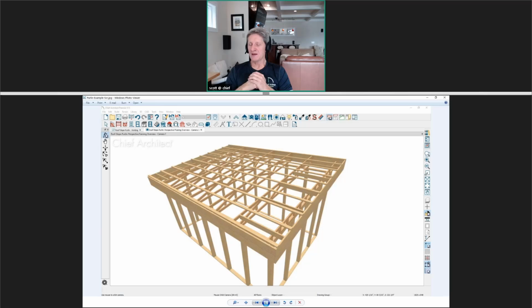Yeah. So the beam currently is basically going to follow whatever your roof is set up as, and on your roof, you can't by edge choose plumb and square. So one of the things you could do is in your elevation view, once you've drawn your beam in there, just trace over that with a polyline solid. You could modify it to be any shape you want. So in one case it's square, in one place it's plumb. And then we'd have to do the same thing for our fascia boards. Well, yeah, it gets more complicated, but that feature, we'll make sure we log it. We don't support it today.